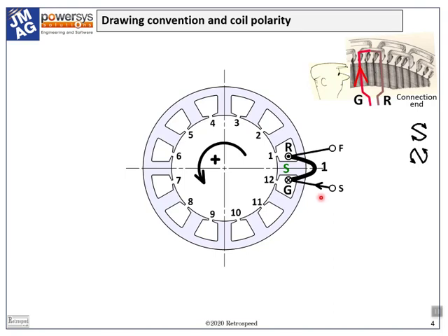When we apply current, the direction of the ampere conductors is the product of the direction of the current and the direction of the conductors. In AC machines, the current typically has a sinusoidal waveform in time, so the ampere conductors alternate in direction and their amplitudes vary sinusoidally with time. The same is true of the magnetic fields produced by the ampere conductors. But of course the coils and conductors remain fixed in the stator.